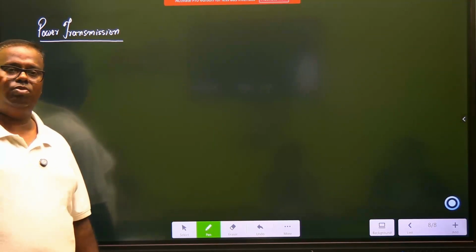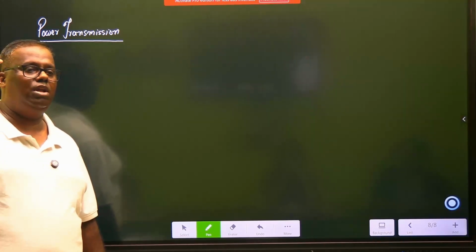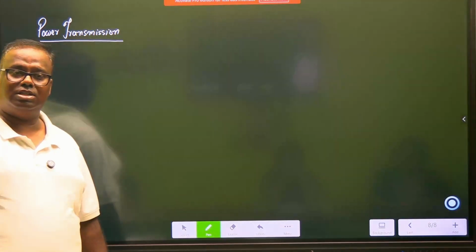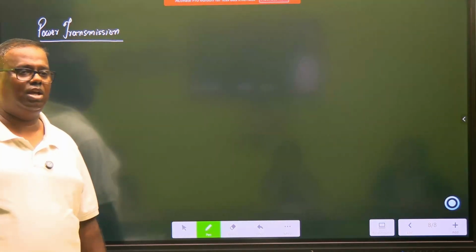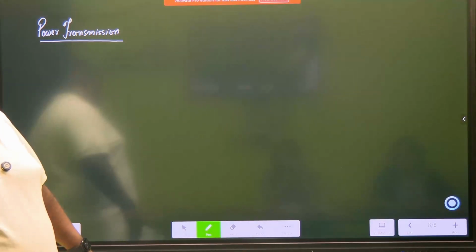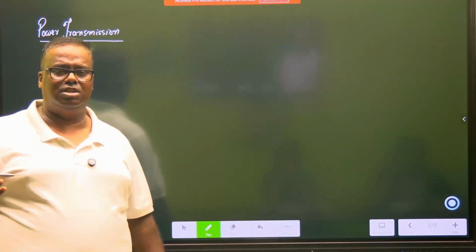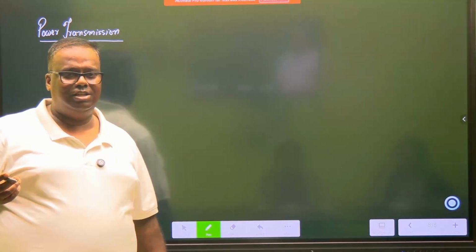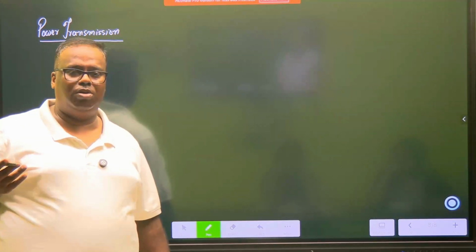So the conductor will have something called I square RT. Now T is 24/7. The resistance of the conductor, I can't have a choice, right? So we will say that, sir, please select wires which are having less resistance. Let's go silver. Pilferage will happen, right? So ideally it goes with copper or it goes with aluminum.